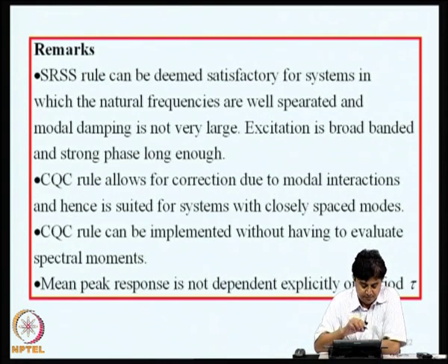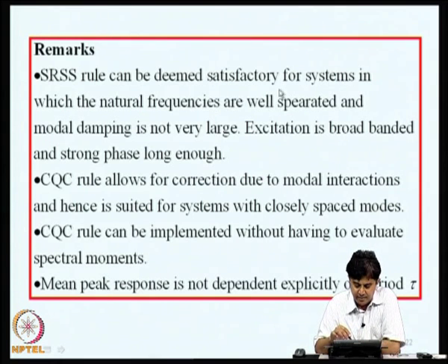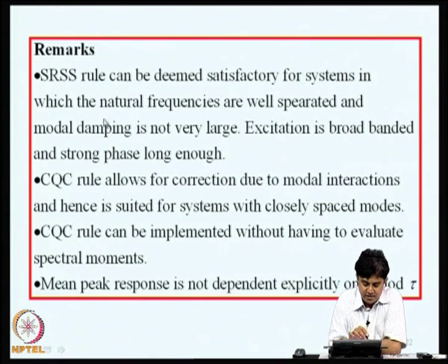A few remarks. This SRSS rule can be deemed satisfactory for systems in which the natural frequencies are well separated and modal damping is not very large. And of course, we also want that excitation is broad banded and the strong phase of the ground shaking is long enough, because we are assuming the excitation to be stationary white noise. So, that requires broadband excitations and excitation to be fairly long, so that the stationarity assumption is justified.